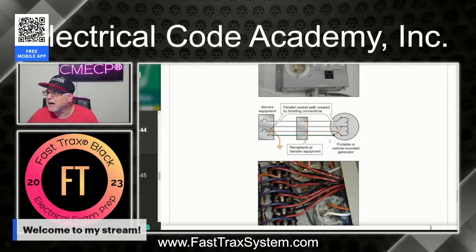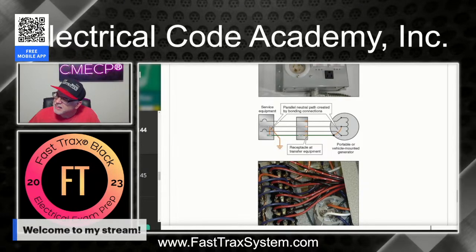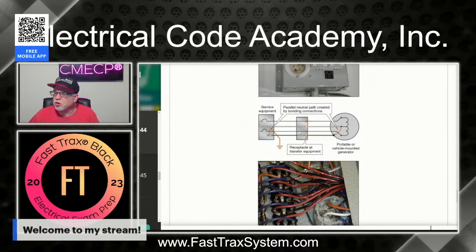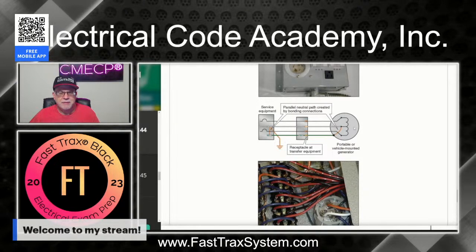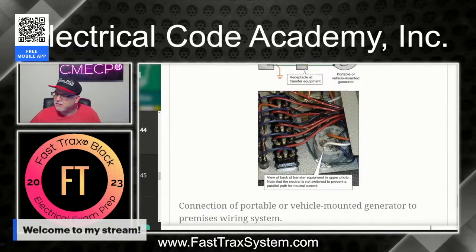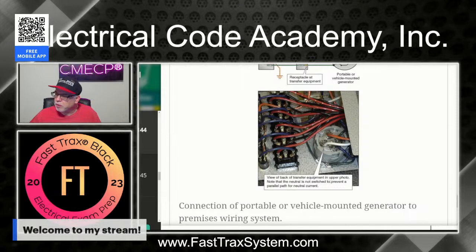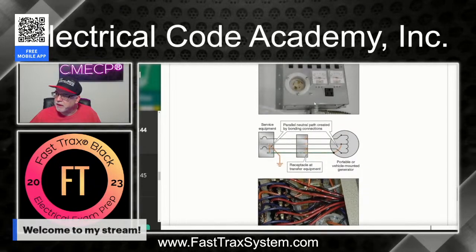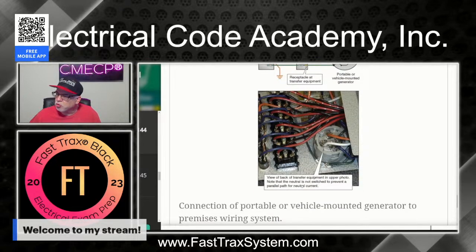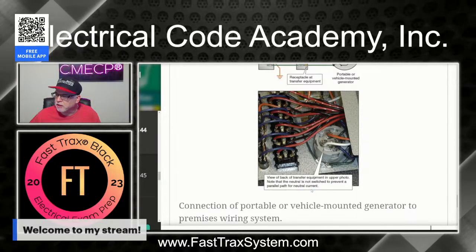All right, so here's what you got. Because this is connected together right here, right? You have to switch the neutral in this transfer equipment, right? Well, this is a problem because they don't switch the neutral. And this piece of equipment, if you look inside of it, you see right here, the transfer equipment, and this is the inside of one of these back here, by the way. This is opened up, turned open. You'll notice that the neutral is not switched to prevent a parallel path for neutral current.